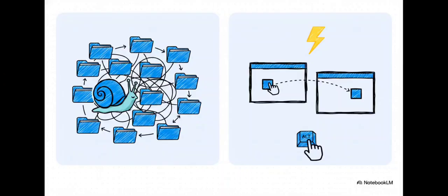Let's pick up the pace a bit and focus on the actual user interface tools that save integrators a massive amount of time. Connecting your logic steps to physical plant tags used to be this incredibly slow, manual 4-step selection process in the old browse dialog. Total headache. Now, Method B offers a fast, highly visual drag-and-drop workflow. You just arrange your CFC and SFC windows side by side and literally drag the connection over.